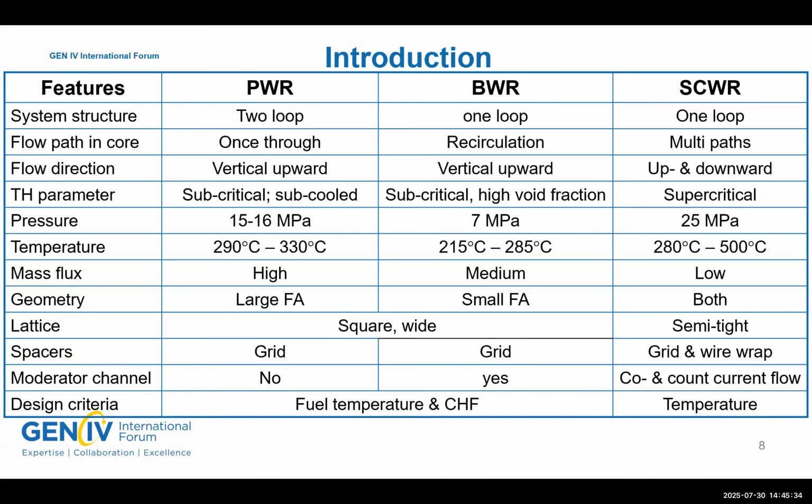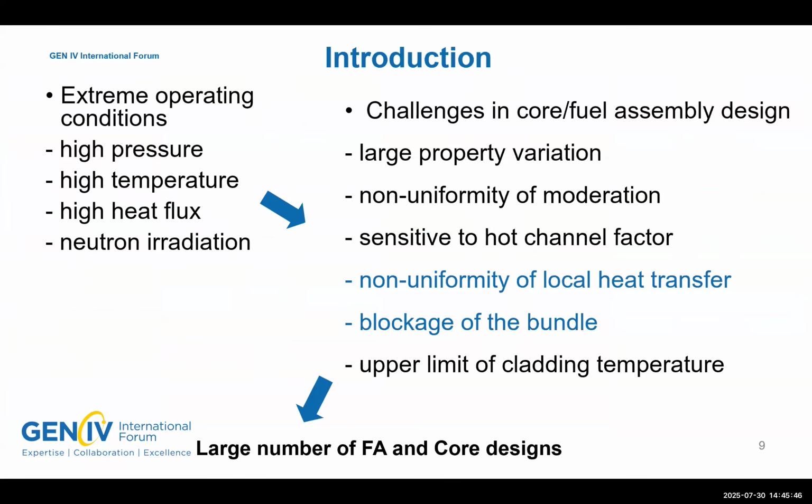And also we have the tight lattice for the fuel assemblies. Both of these, I think, can bring a lot of challenges for the thermohydraulic design of the SCWR. From that last table, you will see that we have extreme operating conditions. That means we have very high pressure, high temperature, high flux, and also neutron radiation, and this will bring challenges for the core and the fuel assembly designs.